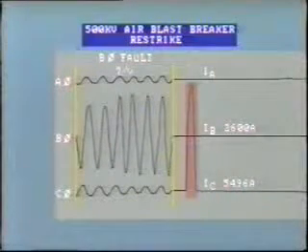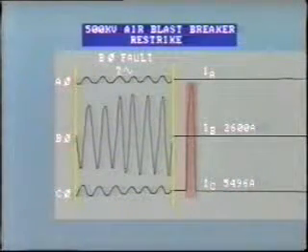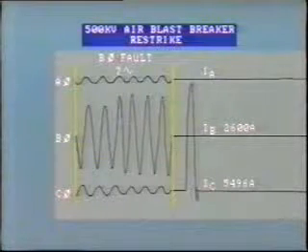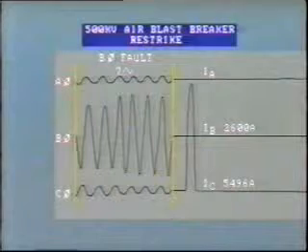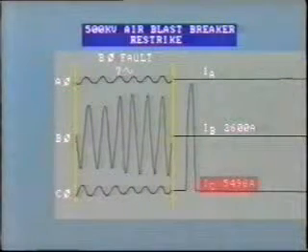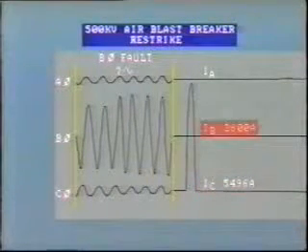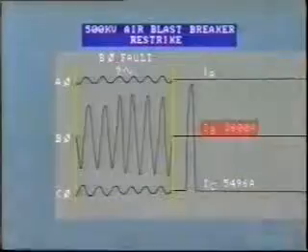Thus, the lightning strike caused both a restrike and a fault. The C phase fault current was extinguished 1/2 cycle later. Notice that the fault on C phase was more than double the magnitude of the initial B phase fault. Well, so much for breaker restrikes. We've seen how oscillogram recordings can be quite useful in spotting this type of breaker performance.